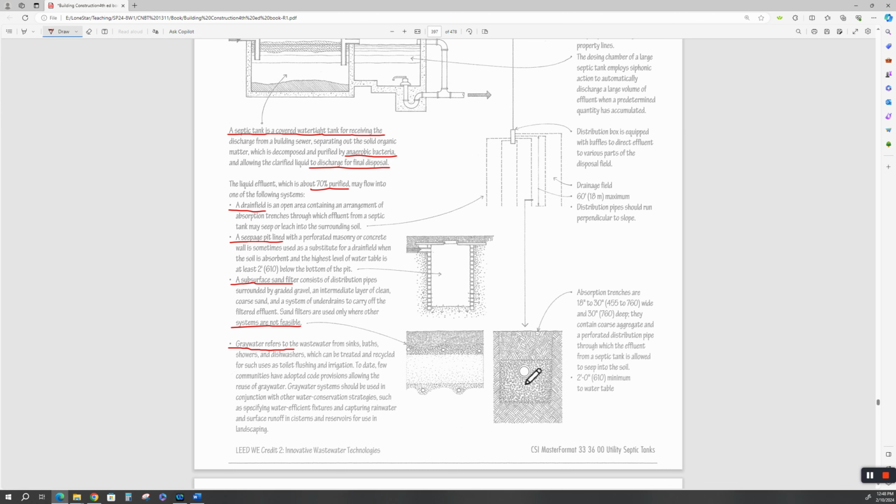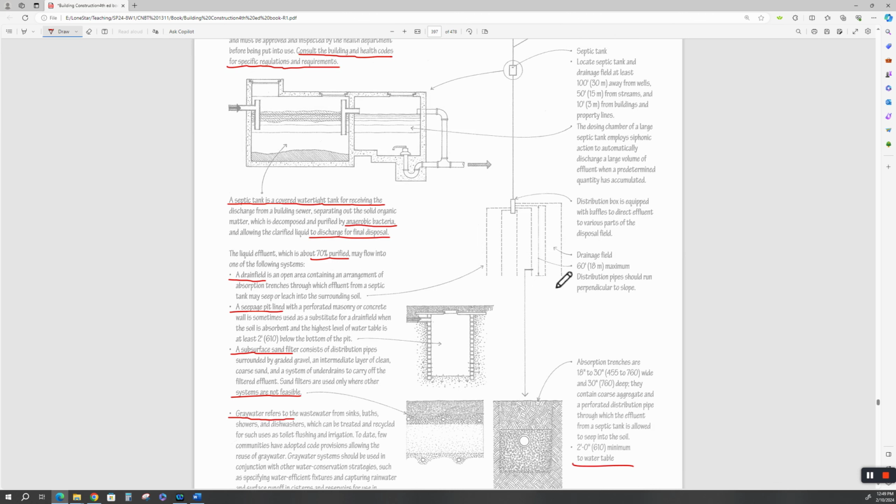These are perforated pipes, and they're set in gravel like a French drain. All right. If you're going to do this, my advice is you wrap this with the geotechnical fabric all the way down this trench so that you don't lose your gravel and then your drain field sinks. Okay, the geotechnical fabric will keep the gravel from mixing with the soil, because remember, this is all water, right? Okay. All right, and then it depends on where your water table is. And all this goes back to the local health code in your area and the building code and everything else. All right.